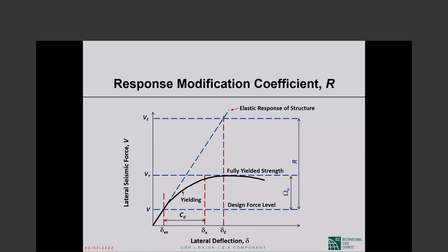Let us say the analysis that produced delta sub xe, the elastic analysis of the structure under code prescribed seismic forces, gives us a bending moment of 100 foot kips at the support section of a beam. Okay, so at the support section of one beam, we calculate a bending moment of 100 foot kips negative under the design earthquake forces.